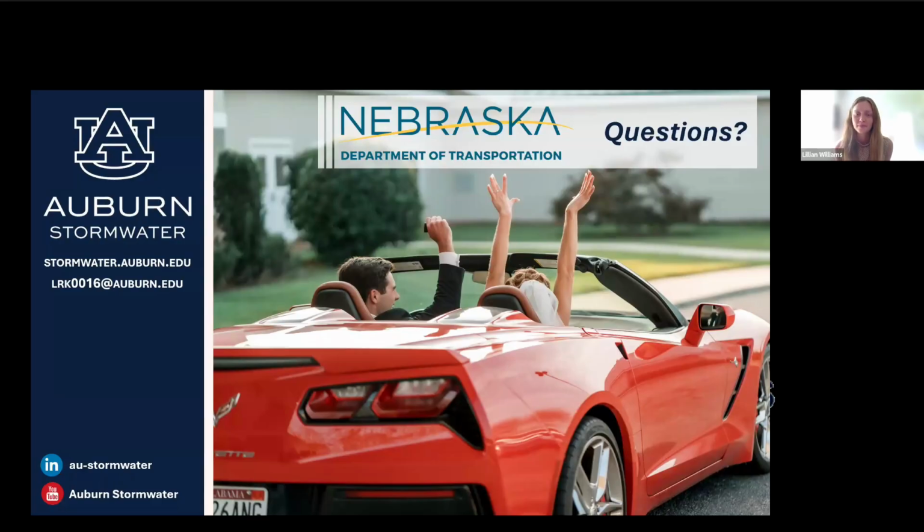We have an attendee here who also asked, how did you repair the holes made by the post to prevent saturating the soil and affecting subsequent tests? So we would replace the geotextile. When we used a lot of the posts for the fences, we would have to completely take out that strip of the geotextile and repair it, like replace it. So that's how we would minimize the holes affecting the tests.